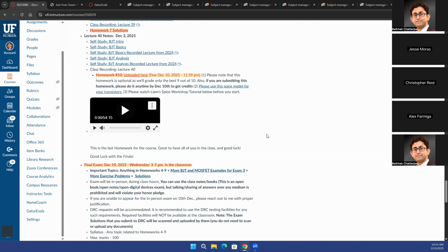But now you know why my input impedance should be infinity, or should not be infinity, and in which conditions it may not be infinity. Let's say you have an input frequency which is very high. In your homework 6, you have seen that if your input frequency is high, the input capacitances may become a short, or something toward a short. In that case, the input impedance may not exactly be infinity at that frequency.